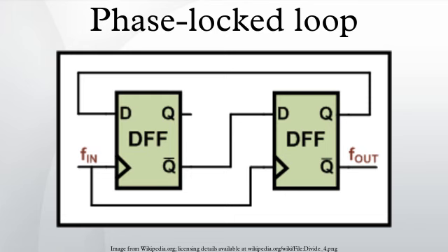Deskewing: if a clock is sent in parallel with data, that clock can be used to sample the data. Because the clock must be received and amplified before it can drive the flip-flops which sample the data, there will be a finite, and process, temperature, and voltage-dependent delay between the detected clock edge and the received data window. This delay limits the frequency at which data can be sent.